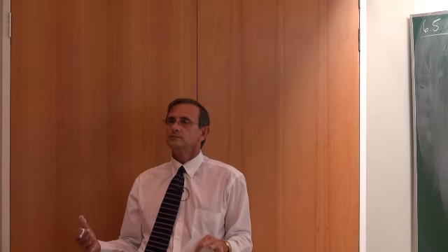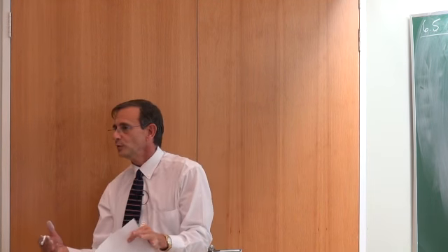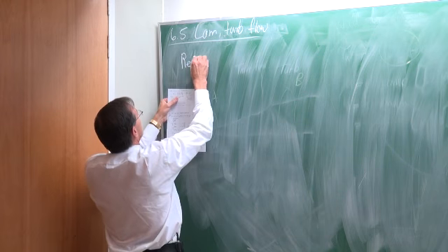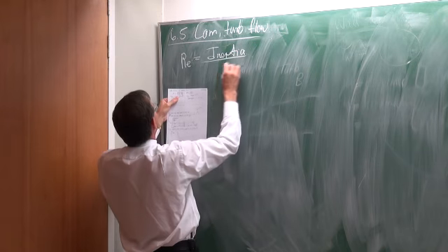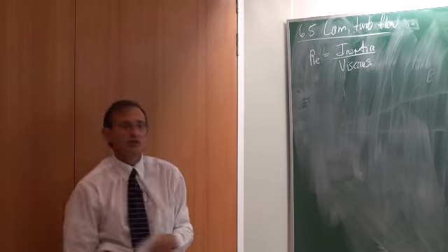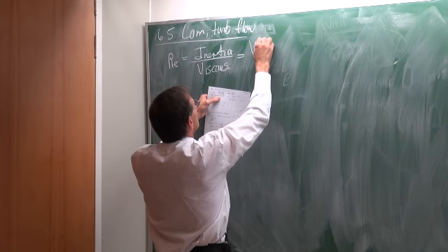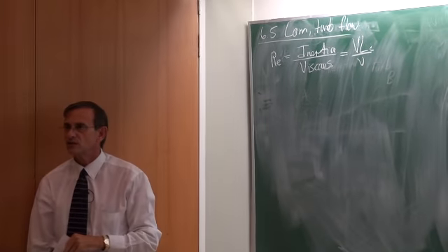Now when we think of laminar or turbulent flow, and to determine when it will be laminar and when it will be turbulent, we immediately need to think of the Reynolds number. The Reynolds number is the ratio of inertia forces to viscous forces, and you can write it as the velocity multiplied by the characteristic length divided by the kinematic viscosity.